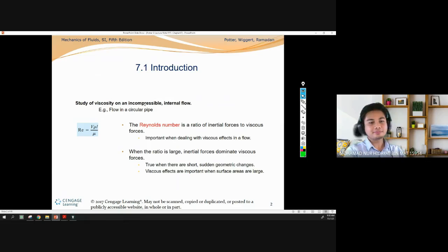Incompressible. Eugene, Naim? Rho not change. Okay, yes. No change in volume. Okay. Yes, basically the correct statement is incompressible means density is constant, no change at all. For example, there is water flow and the density of water is always 1000 kilogram per meter cubed, and will not change from point 1 to point 2 to point 3. It is constant. So we call it the incompressible flow.